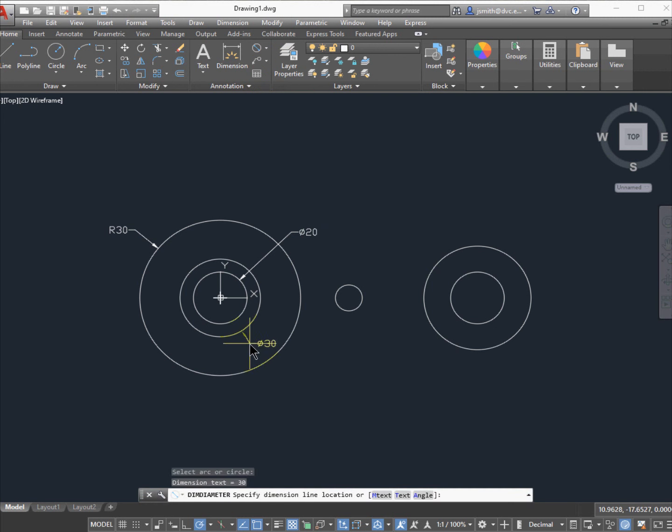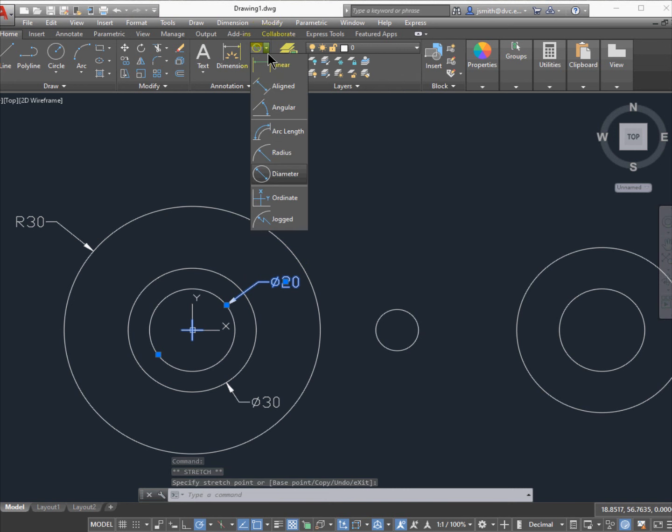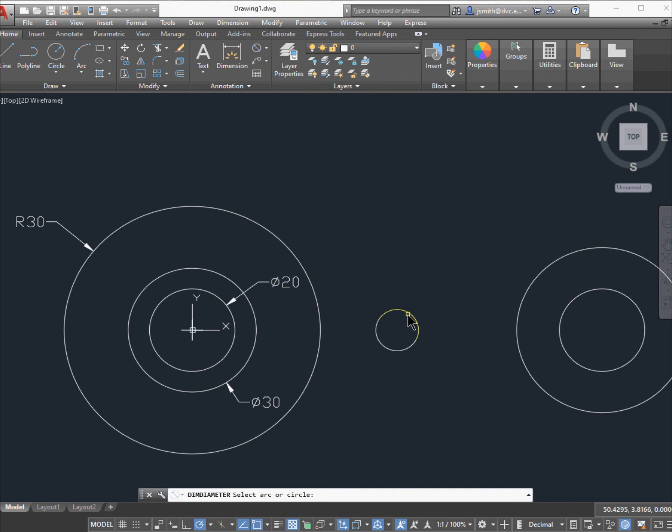I do this in my videos this way just to make sure you see it and you don't know when I'm actually hitting my enter key. But after you do a command and you push enter, it'll do the same command the next time around too. So again, I am dimensioning this, confirming it, but I'm also toggling back and forth with my drawing. All right, so I want to verify the dimensions, but also make the dimensions.